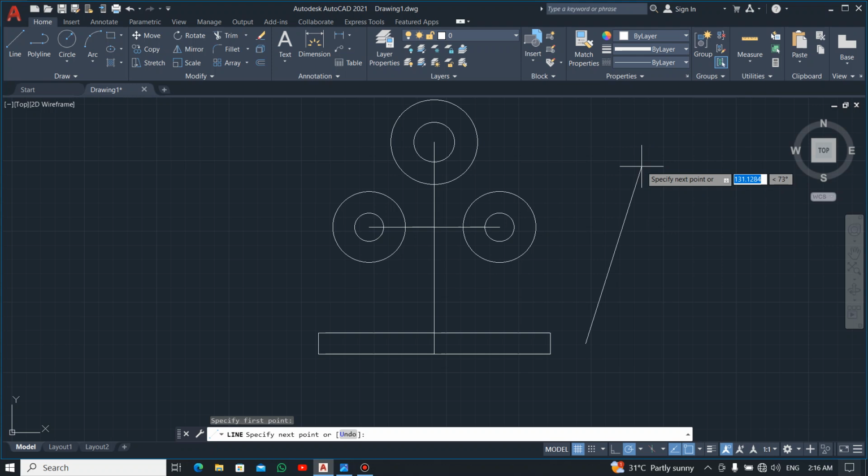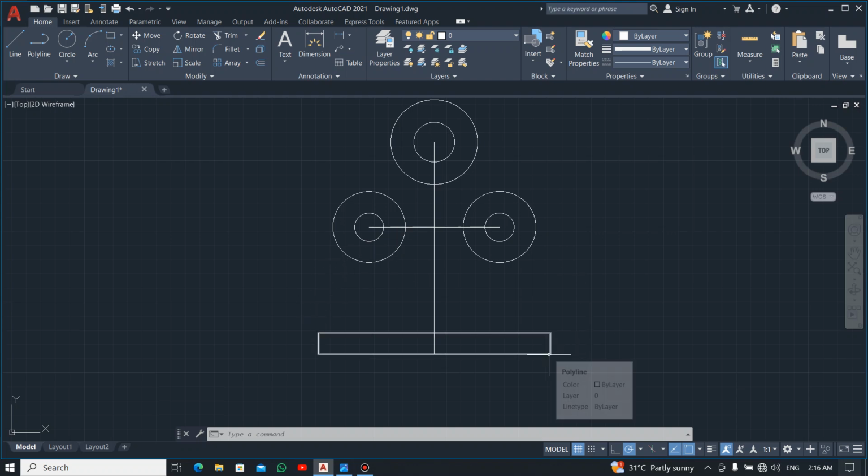Now AutoCAD reads the angle from the right, it reads it anti-clockwise. So it reads it this way, from this side to this side. So here is 0. Whenever you are drawing an angle, here is 0. Now when it moves like this, 0, 1, 2, 3, 4, 5, 6, up to this side, you get 90 degrees. Then from 90 degrees, coming down here, 100, come here to 180. All right, so now we want the angle in between the two lines to be 46.